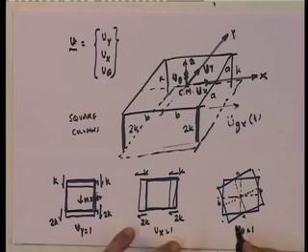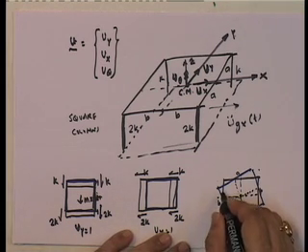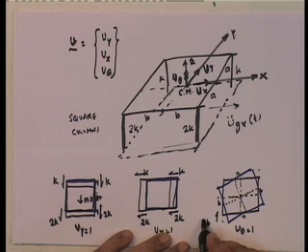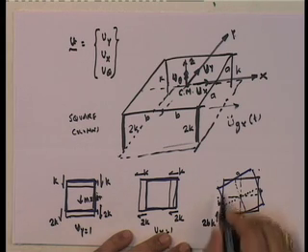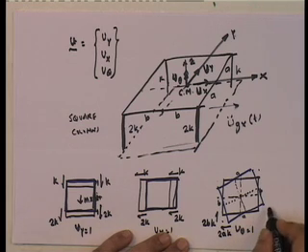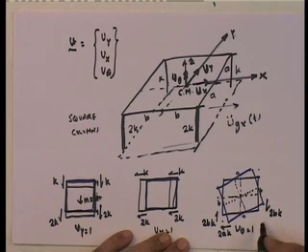So, therefore, if I were to draw it, since this has gone this way by B, at this point I have 2bk here upwards. Since this has gone this way, it will also have a force here, and that is equal to A into 2k, so 2ak. Similarly, this one, since it has gone up, it will be coming down, and this is equal to 2bk.